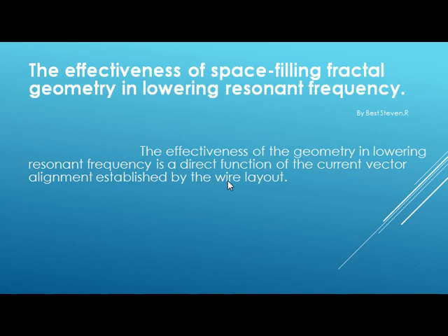Can you take the fractal antenna and mount it in a parabolic focusing configuration so that it only gives you a beam in one direction? For example, a point source radiator that comes off the tower, the power is inversely proportional to the square of the distance, but the effective radiated power gives you gain that's flat because they don't want to radiate straight up. So they create gain in the plane by adjusting the elements in the antenna.